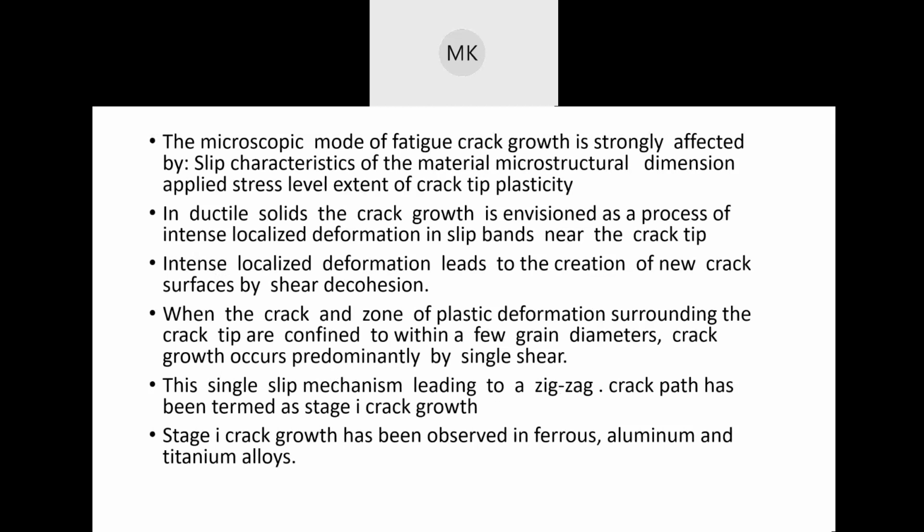So the microscopic, when you start looking at the fatigue cracks under a microscope, it is strongly controlled by the slip characteristics or the direction of the slip planes or the persistent slip planes, and also the microstructural size that we are looking at, and also the size of the load that you're applying. If the loads are high, you will see certain slip planes, and then that's it, the crack would initiate and grow. But if the load is really low, you would see a lot of slip planes getting connected at a lot of different places, and that's the major difference that you're going to see in terms of looking at it microstructurally.